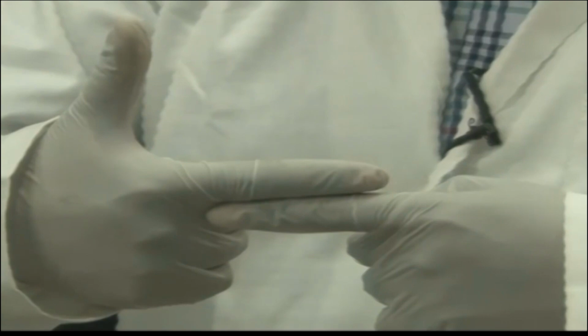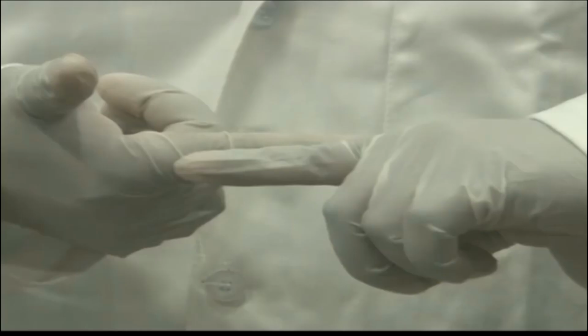So how much overlap can we keep here? If this overlap is not here, and this is 0.1 and this is 0.1, the nozzle will touch this one and might get displaced, and the part might distort. So some overlap should be there, some gap at this surface for the nozzle to work in. For that, this overlap limit is given, and it can be 15% or 20%.